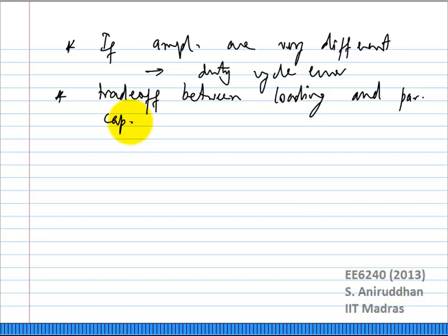So I'll have to reduce the resistance and increase the capacitance so that it does not depend on parasitics. If I do that, I'll have to burn more current to get the same bandwidth or the same loading, to take care of these loading effects. Higher current at higher frequencies, if you want to compensate for this parasitic capacitance.